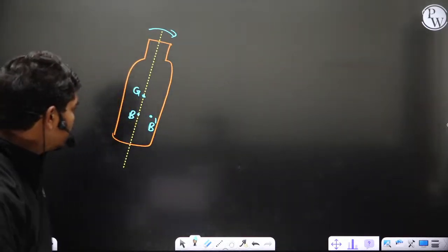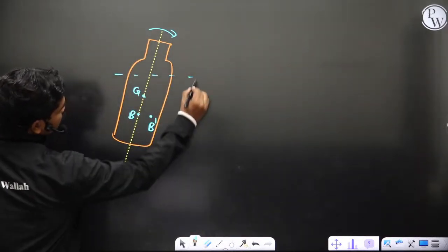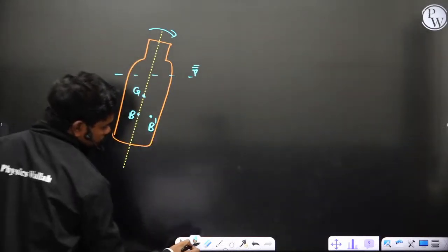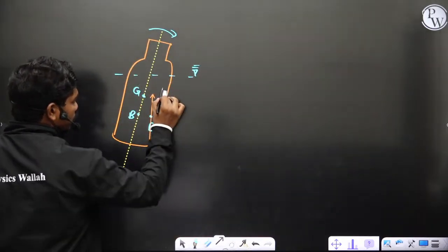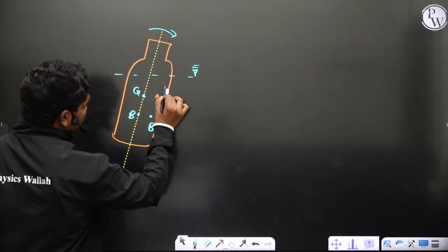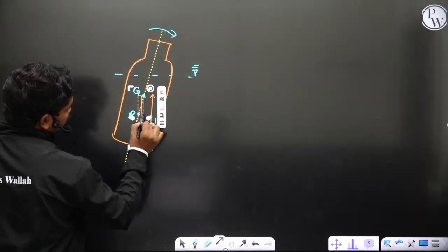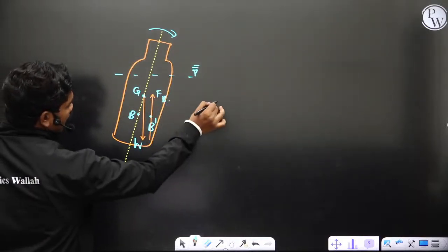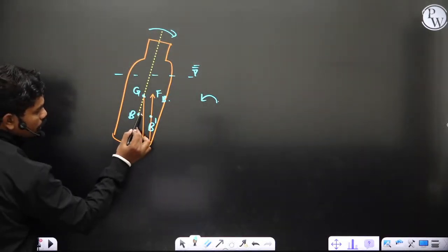Now in this case you can see, because of this tilting, suppose this is the free surface, then if buoyancy gets shifted from here to here, this is the buoyancy FB, and clearly this is the weight, here. So this is weight and this is buoyancy, and this is producing an anti-clockwise couple. But let us suppose instead of B going to this point, it landed up here, for example.